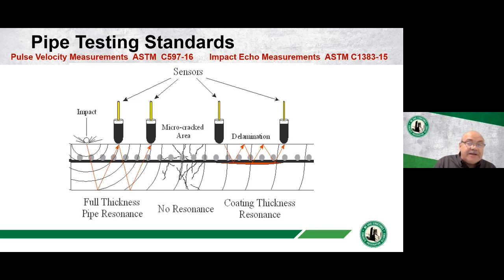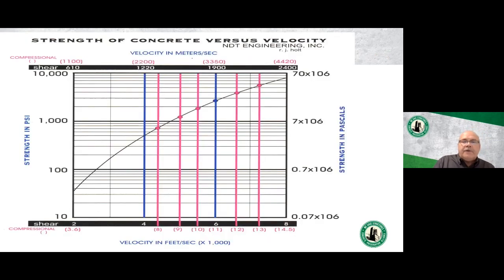If there's a debonding or a delamination of those pre-stressing strands from the concrete in this diagram, that thickness frequency is going to change. Maybe it's going to go from 5.5 inches down to 2 inches. And it's still the same pipe, but that tells us that there's an air gap, and that air gap corresponds to a debonding or a delamination of one of these components of the pipe.